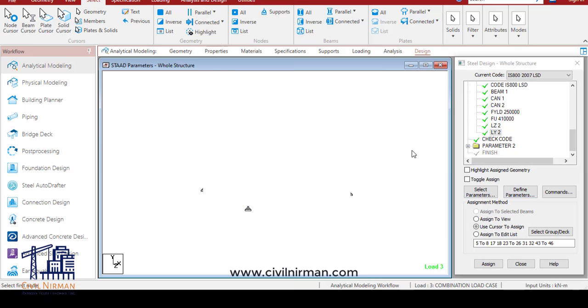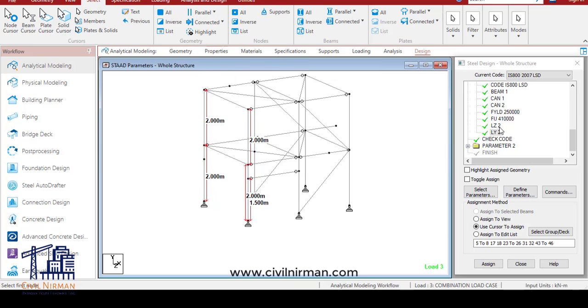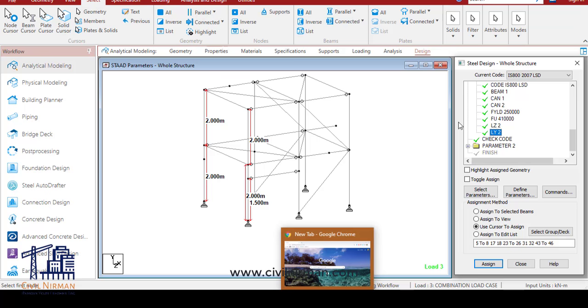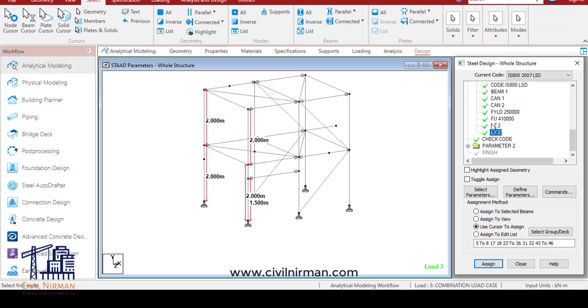So this was about the concept of defining the effective length of a member. I hope you understood that. Now there is another practice that is going on, that at certain times we can avoid this kz and ky, and simply multiply this factor into that particular direction of length.